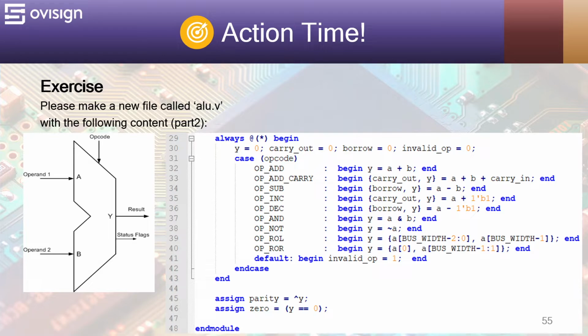We used 1'b1 instead of 1, so the synthesis program uses an 8-bit adder or subtractor, otherwise it would treat it as an integer operation on 32 bits. This happens only for some synthesis tools like Intel Quartus.